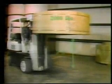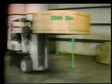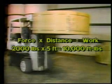If the forklift exerts a force of 2,000 pounds over a distance of 5 feet, then, according to our equation, we have 2,000 pounds of force times a distance of 5 feet equals 10,000 foot-pounds of work.